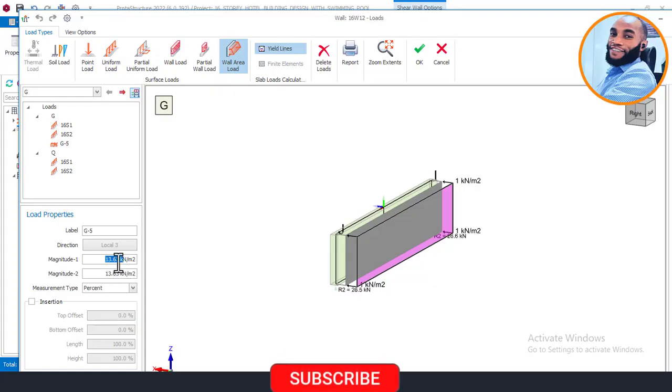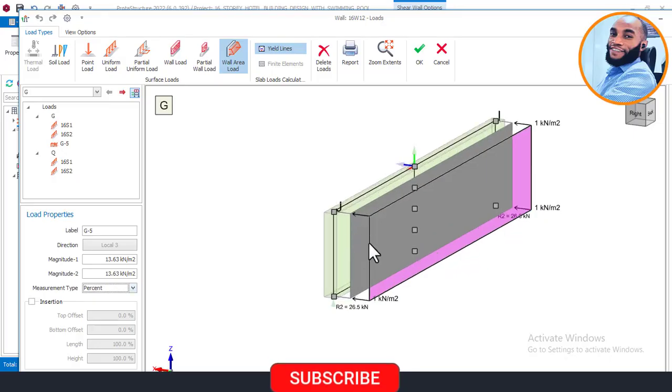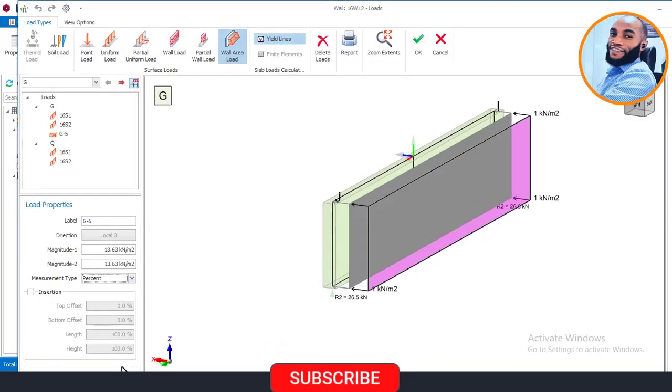Right now, once you have inputted your values for magnitude 1 and magnitude 2, for the place that says measurement types, I would say you should leave it at percentage, because if you leave it at distance, it means you know where the water will stop and all that. I want to leave it as percentage because I want the load to be taken by the full wall. So I'll leave it as percentage, and then I will come here and click on update.